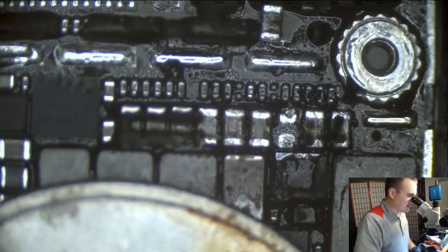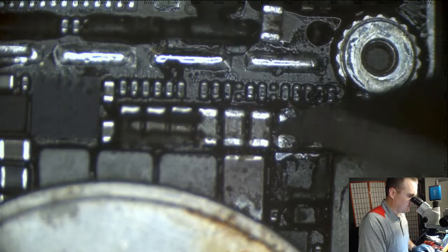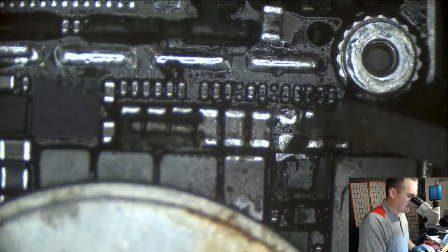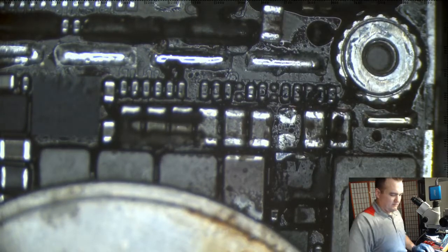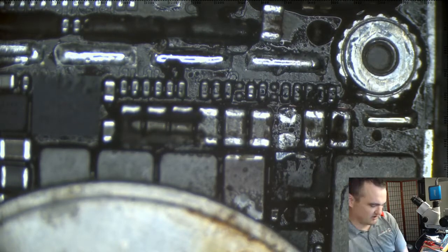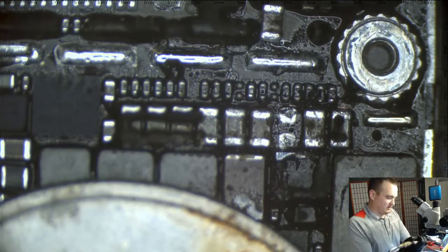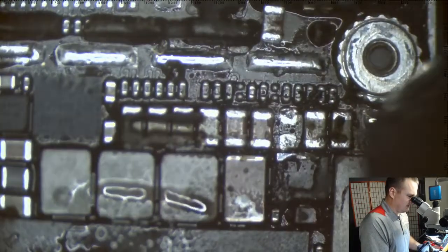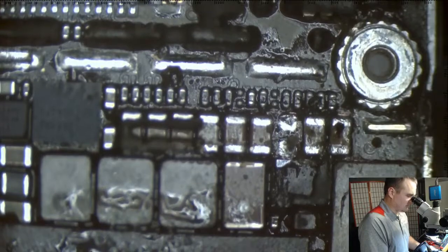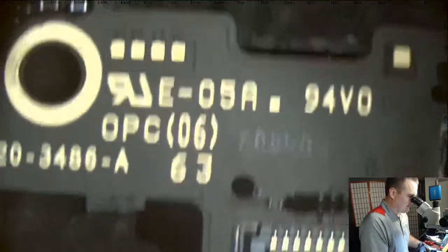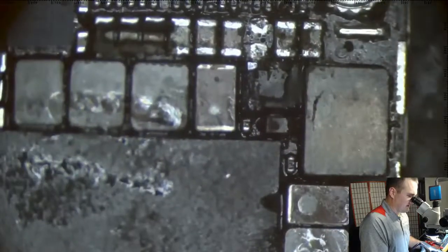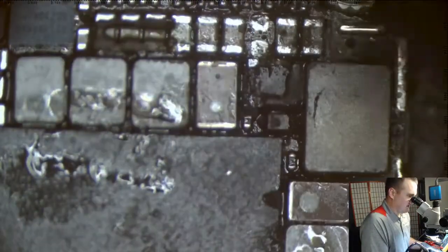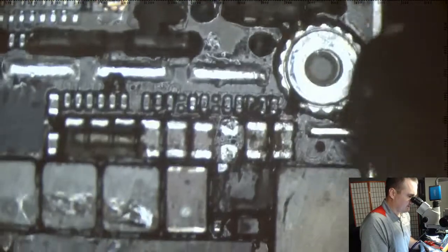Now, let's not lose track of what we're actually trying to do here. All right, so I just picked a backlight anode cap to pull off, and I set it to the side. I'm gonna cool the board off a little bit so we can get an accurate diode reading. As accurate as can be reasonably expected. I'm gonna blow that capacitor away. She gone. Right, so if that wasn't the culprit, then we'll pull one off a donor board and replace it.